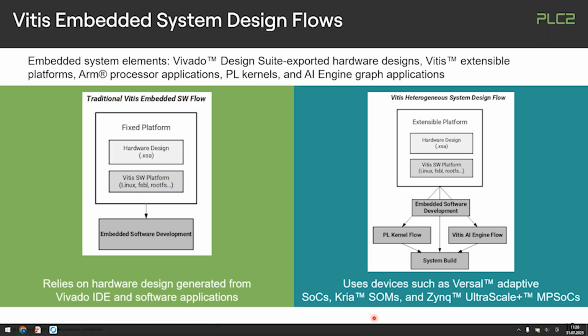So let me just claim that this process is not just there for Versal. What we do building an extensible platform, we can do for the Zynq UltraScale+, we can do for the Kria SOMs, we can do for any of these adaptive SoC-based platforms, and it's the same thing. So you're building an HDL plus CPU level or PS system level configuration as a base that doesn't necessarily hold your final functionality. And then you go into kernel-based development inside Vitis, software-defined development of these elements that you functionally want to have.